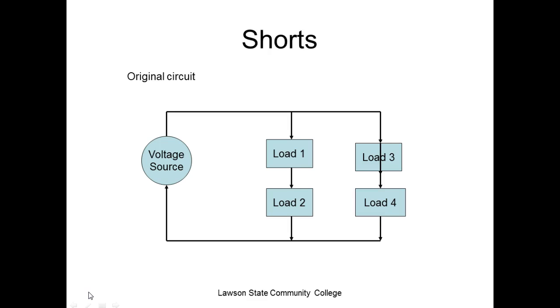So this is a short right here. Notice we've got a series-parallel circuit, and this load right here is bypassed. So what would happen to the resistance? Well, the resistance is going to go down, and the current in the circuit is going to go up. Would this blow a fuse? Probably not.